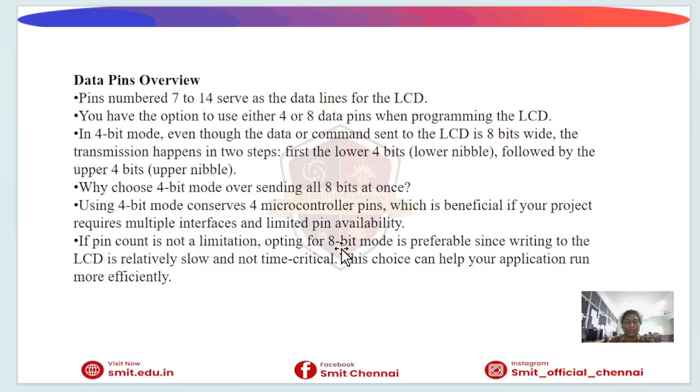In 4-bit mode, it uses only 4 data lines and sends the data in 2 parts, 4 bits for one part and 4 bits for the other part.